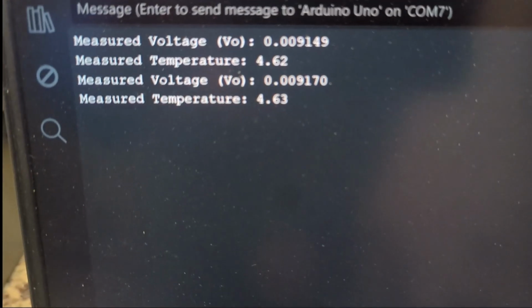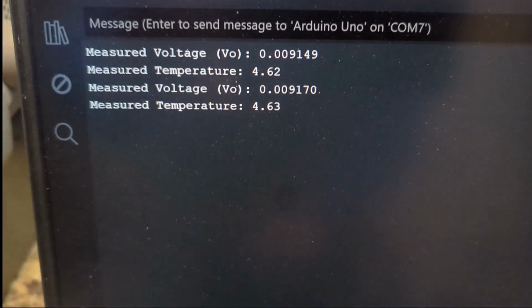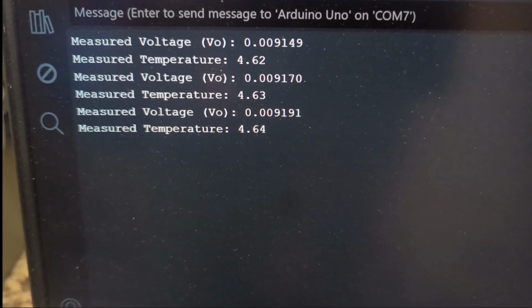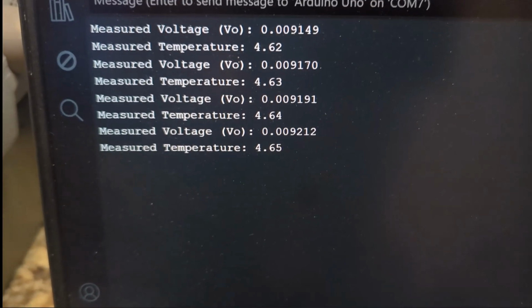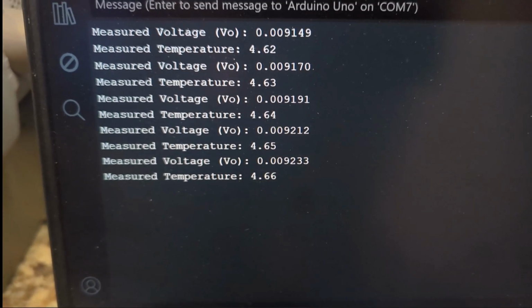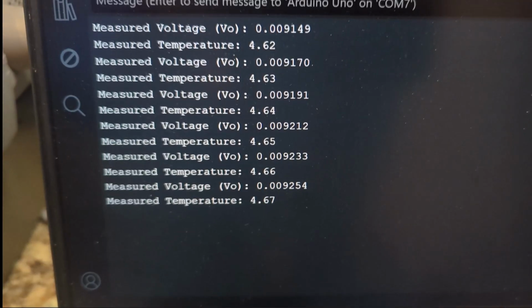If you notice from the other demo, the measurements are taking longer to print out. That's because I'm doing a longer averaging time and more filtering with my Sigma Delta ADC. Okay, I'm going to pause it right there. So notice that the measurements, first of all, are almost exactly the same as what you saw on the DMM. So that's a good correlation for a reference. And we can see we're getting that very high precision. I have even higher precision set on these measurements, so we can see down to the microvolt of this measurement.